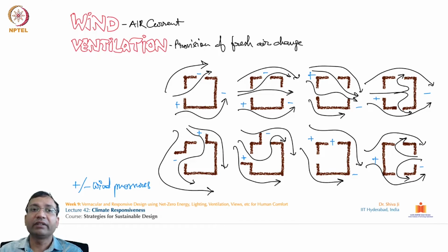Even if the wind is not very fast, how can we create high pressure and low pressure micro zones to induce the wind inside our premises? This slide talks about that. How can we promote cross ventilation, and a staggered way of wind movement, and if it is not needed, how can we avoid it?